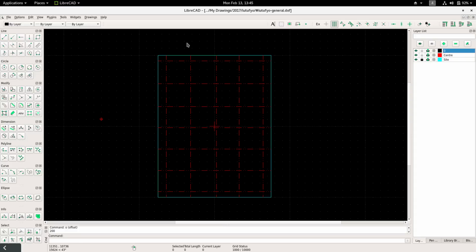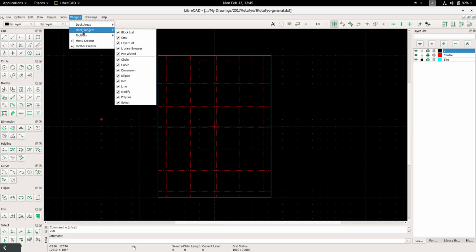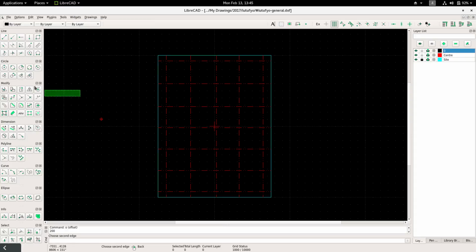made, personalized from Librecad defaults. At the left here we'll have what they call a dock. I use left dock, right dock and bottom dock, and very few toolbars, and that toolbar is this one, and the snapping one, and the layer organizer. So with this layout, I have everything that I need to work my project from scratch to finish.